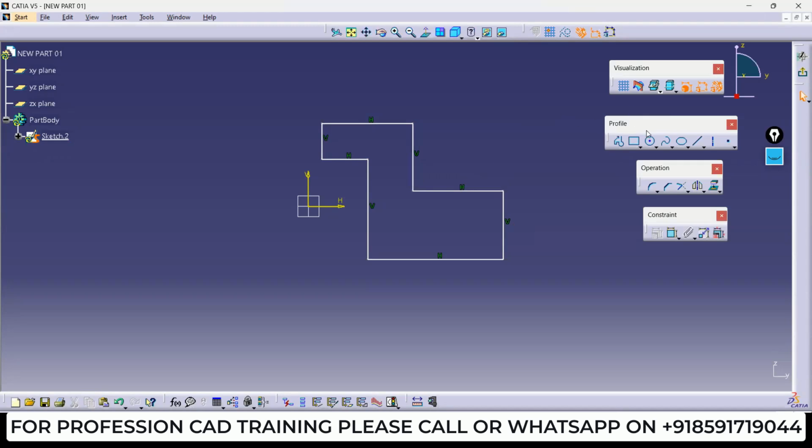But here in the constraint toolbar, if I select the second option, constraint, and give a dimension to this line, say 95.126, you can see this line turns green. What does this mean? It means this line is now fully constrained. This line can only travel in this direction. It cannot travel in this one because this dimension is locked here.